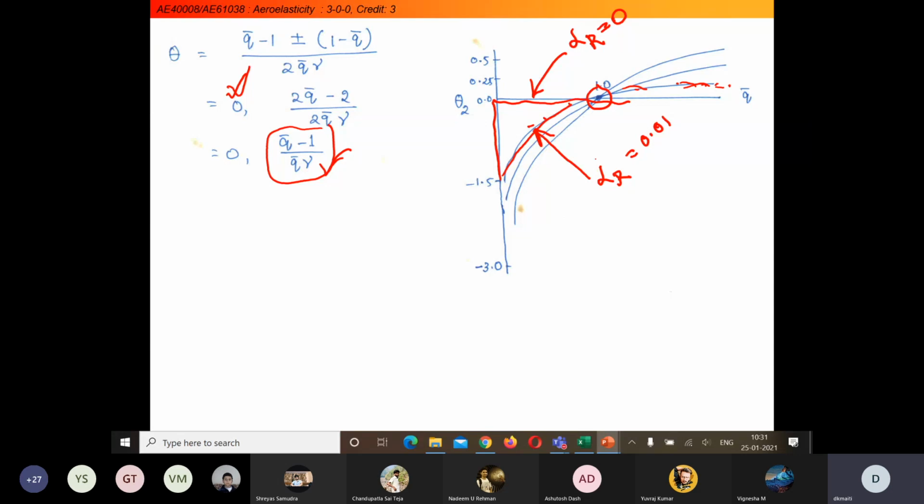We can apply the energy theorem and calculate the total potential energy, from both structural stiffness and aerodynamic stiffness, considering nonlinearity. Then we can find the point where it will be unstable: taking the second derivative of total potential equal to 0, we can find the value of theta.